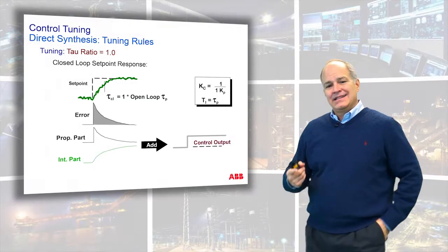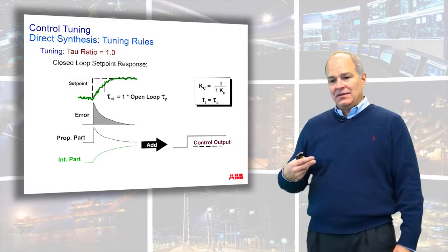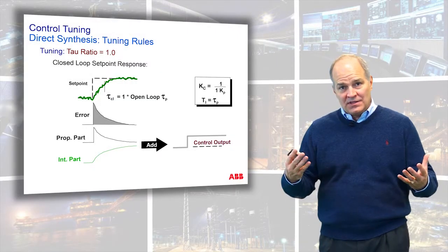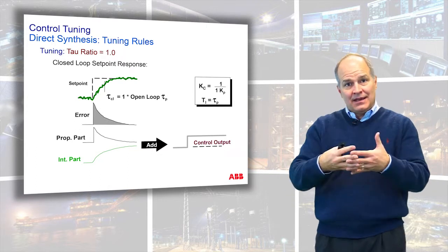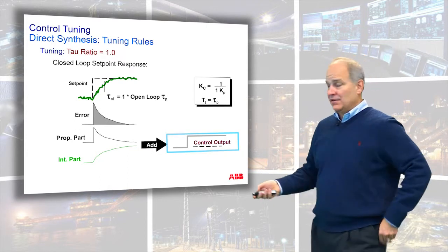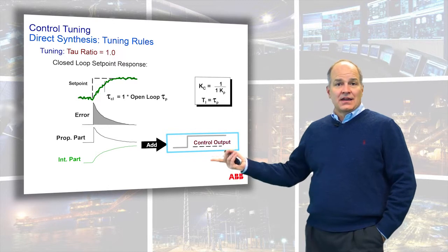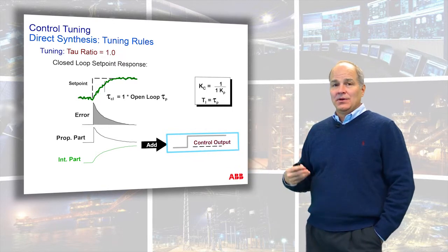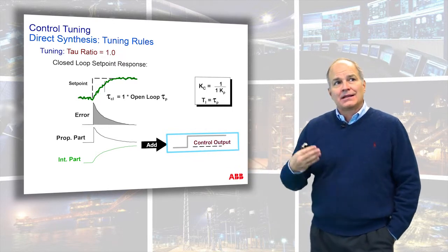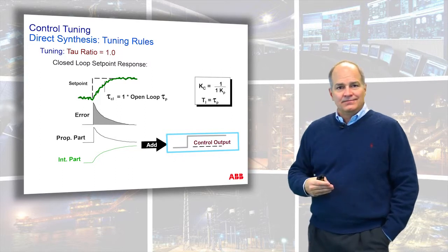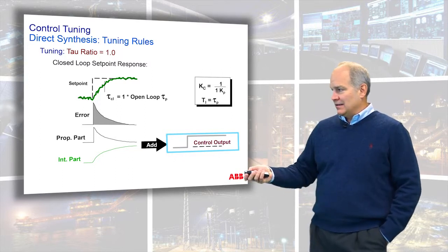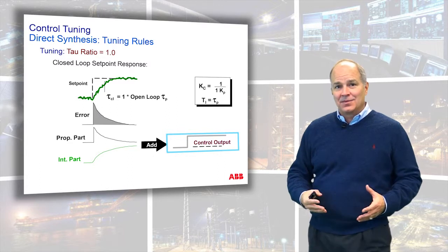You never get to see the proportional acting by itself and the integral acting by itself. You always see the proportional integral acting together. So you see the output of your controller, and it looks like it was a step change. And a lot of people will incorrectly say, well, it's just a proportional correction. No, it's a perfectly calibrated loop.